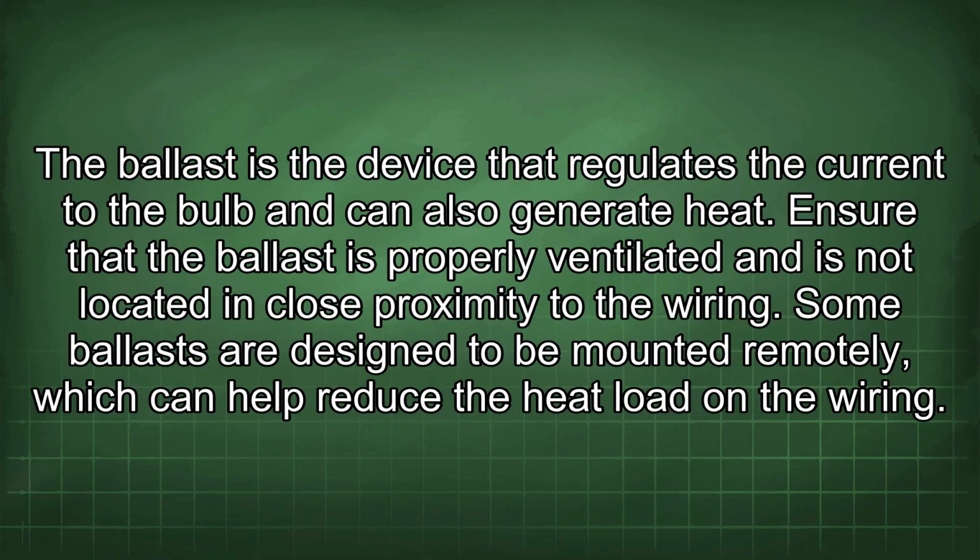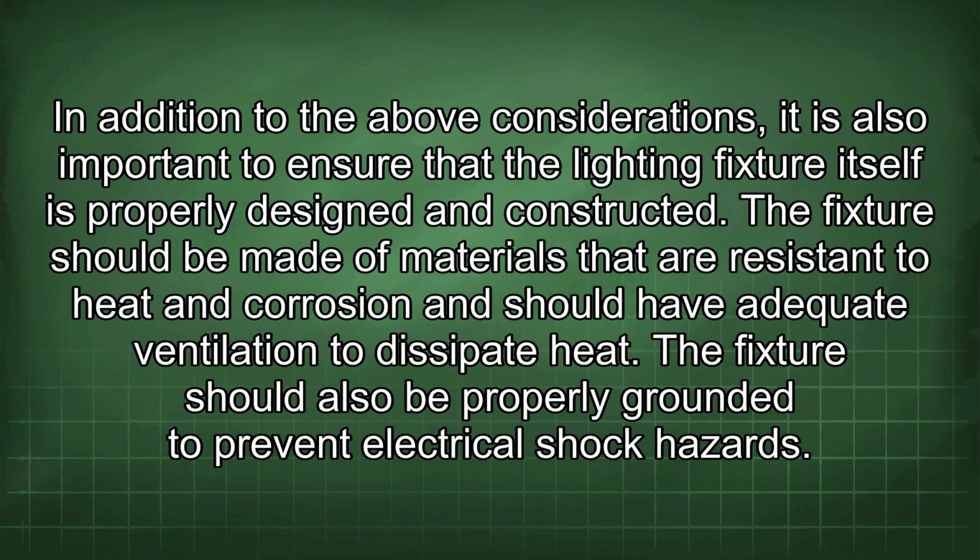Some ballasts are designed to be mounted remotely, which can help reduce the heat load in the wiring. In addition to the above considerations, it is also important to ensure that the lighting fixture itself is properly designed and constructed. The fixture should be made of materials that are resistant to heat and corrosion and should have adequate ventilation to dissipate heat. The fixture should also be properly grounded to prevent electrical shock hazards.